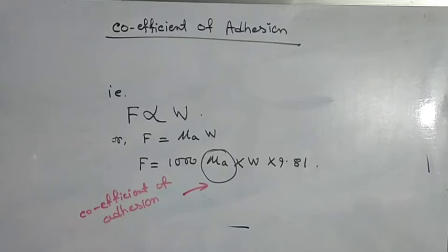And this is why the starting of traction motors either by the series parallel method, or by the rheostatic method, or by the tap changing method is inferior to the method where applied voltage is smoothly and continuously varied, such as by means of grid control in vacuum tubes or by gate control in the case of silicon controlled rectifiers.